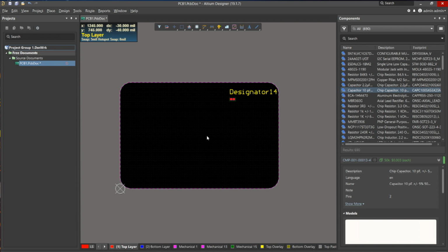The problem is when I have a lot of DXF files, we're using very organic shapes. Okay. Splines, Bezier curves, whatever, Altium can't handle that. Right. Anything that's not a straight line or an arc, it just blows up. Yeah, and even if it is going to bring it in, it's going to bring it in as a couple hundred primitives, as we see on some arcs, and that's kind of like your best case scenario. So that would be something to discuss with the mechanical side of things, of how they can simplify that.